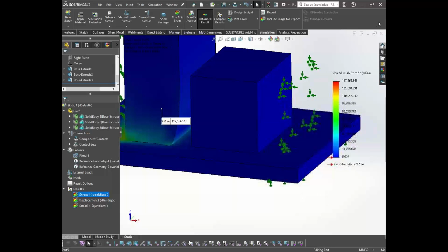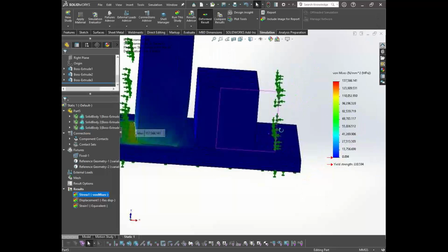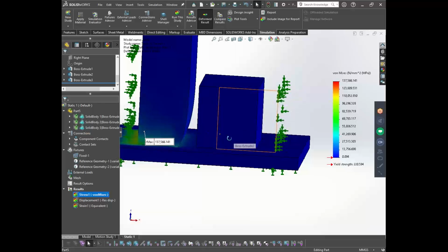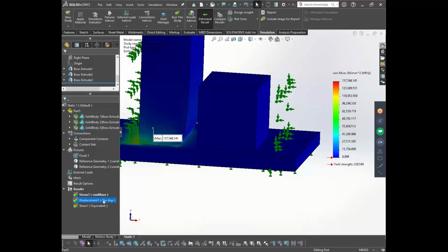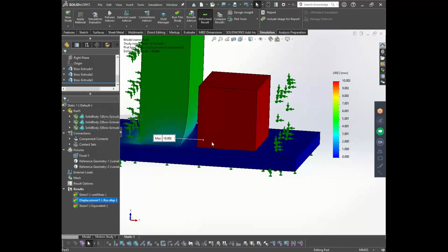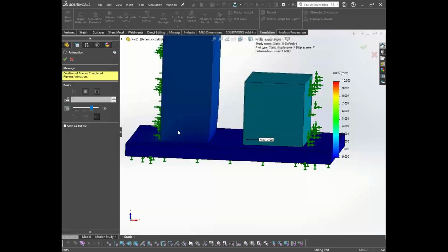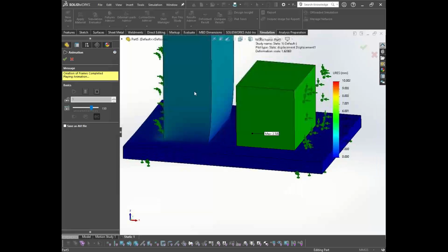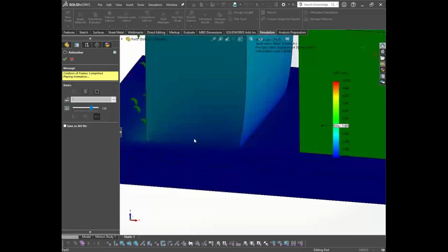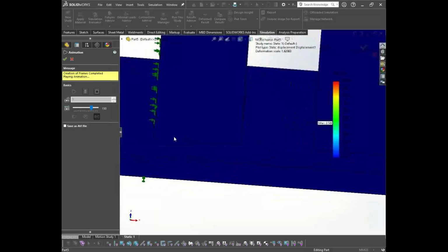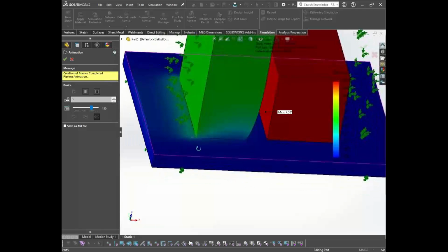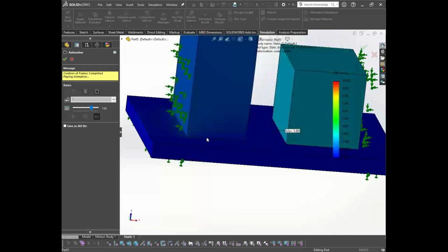okay. So earlier you observed that it was trying to stop it from moving forward, but when I applied the no penetration contact, now this part can move easily. But since the global bonded contact is defined and we have not defined the contact between these two components, it is unable to move forward. Can you see here? The bottom of this, it is stuck.